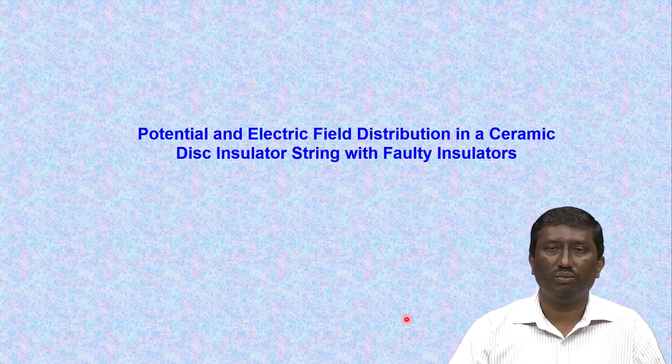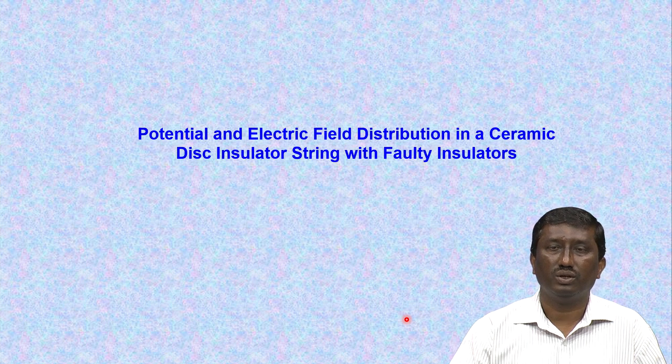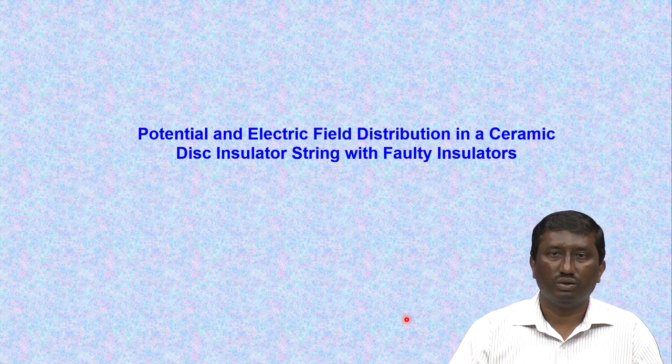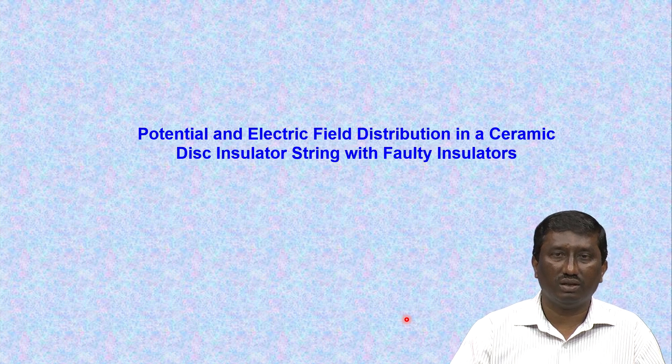So, this could happen because of the failure of insulators due to tension loads or because of inherent property of the insulator which could have failed over a period of time, losing its insulating properties. So, in case the insulator position where the failure has happened is very important.